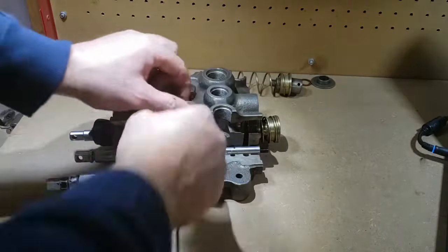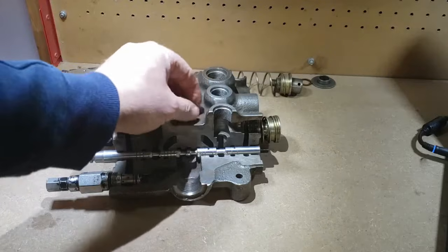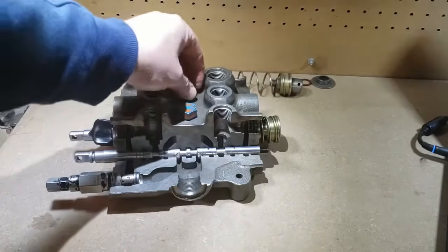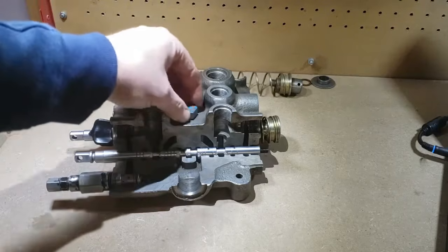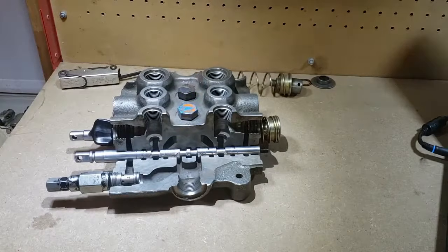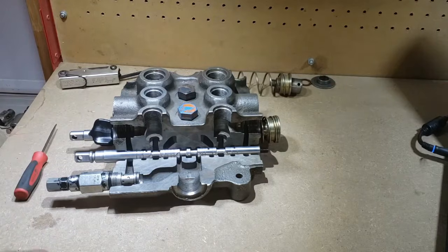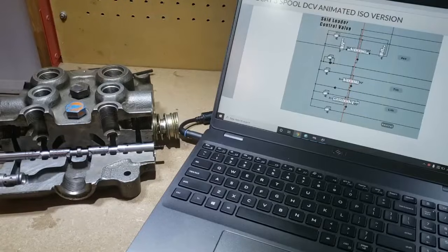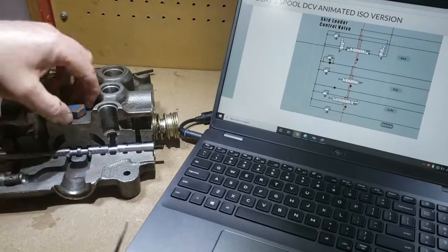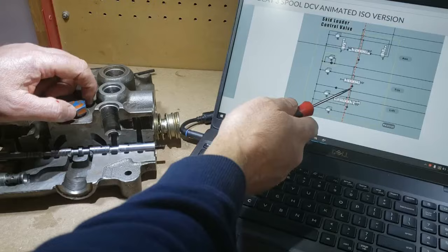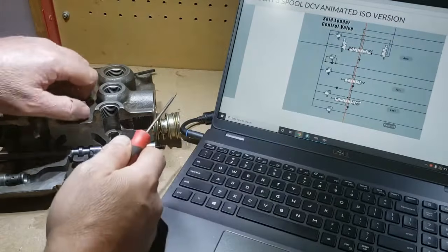So load checks, pretty common to find those on open center valves in between the 2 work ports if there's room. Sometimes on smaller DCVs they get a little creative with where they install those, but functionally they're upstream of each spool. If we look at those on the schematic, those load check valves are here, one for lift, one for tilt, one for auxiliary.